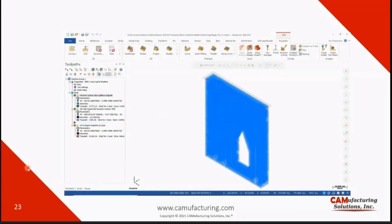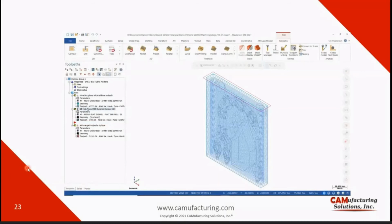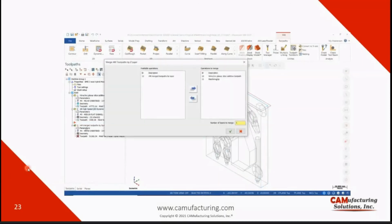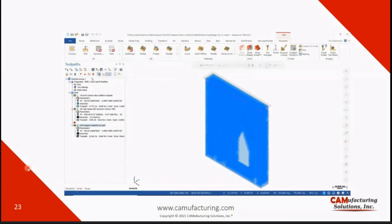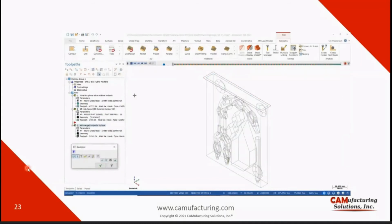So let's have a deeper look at this example. This is the wire arc toolpath, the additive one. This is the subtractive toolpath, the 2D dynamic contour, and this is the layer merge by APlus. You can choose how many layers you want to merge. I regenerate it, and I'm going to show you the back plot. So we will have the first layer of additive. When it's deposited, we are going to have first layer of machining, second layer of additive, second layer of machining, and then we are going to do the same to the top.